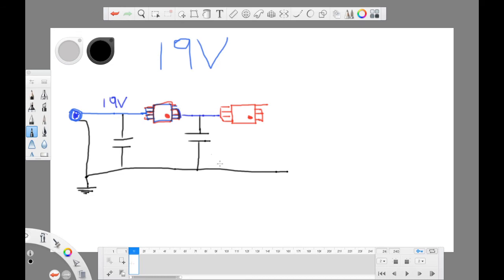Remember, here we have a DC. This is 19 volts DC. It's a direct current. So we'll try by all means to remove the unnecessary frequencies, the unnecessary noise, all those things. We'll try to remove the AC. Okay, we're trying to remove the AC by using the ceramic capacitors, even the diode as well. Okay, so it can be anything. So after the MOSFETs, you will have 19 volts going all over.